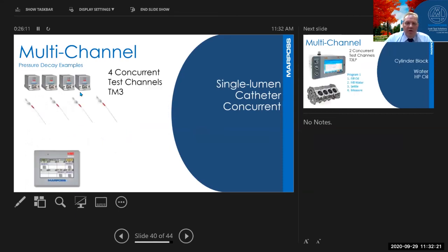If we're looking at a single lumen catheter concurrent, what we can do is with our TM3 series, we're able to tie these all in independently and check 4 concurrently this way. 1 start signal, all 4 parts are tested. So an operator would load 4 parts, hit start, and off you go.